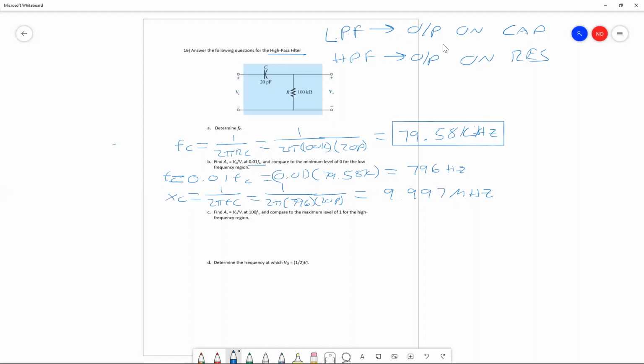Finally, we will plug in the value we need for this gain equation. So this is for a high pass circuit. Okay, so you're going to want to use that high pass side, which is the right side, and that's going to be 1 over square root of XC over R squared plus 1. We'll plug in the numbers.